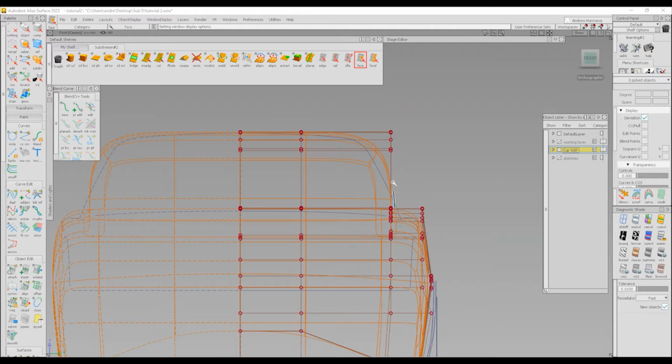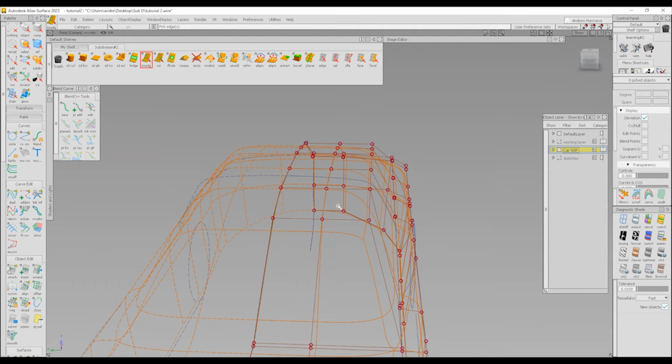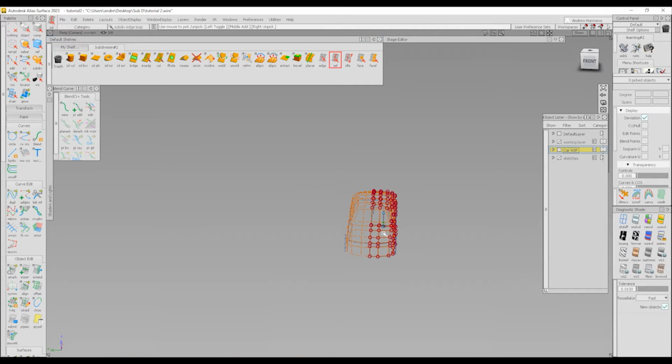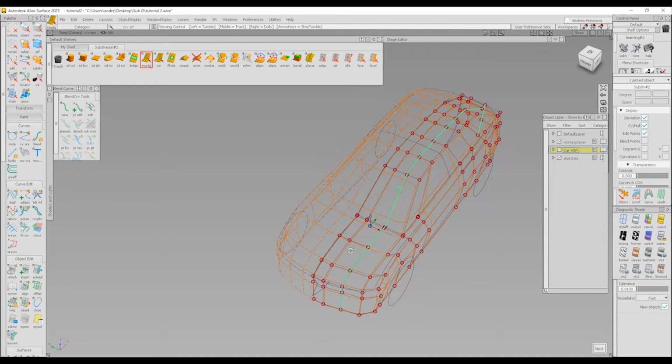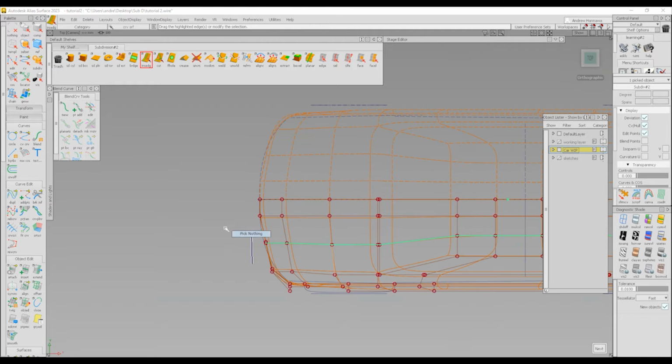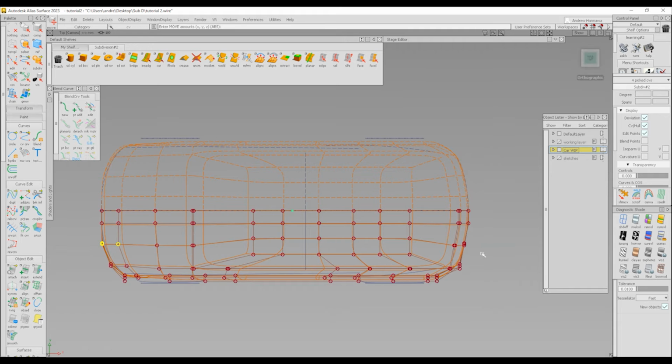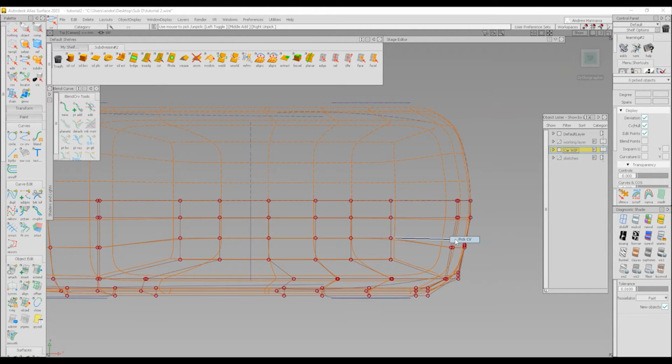We can go into the front view, and then we can add a little bit more tumble home to the car. It looks like we have too much shoulder. We can edit that. And then maybe we can move this symmetry edge loop a little bit further inward, so we can add another one and add a little bit more control in our plan view. So I'm going to be moving these CVs and add a little bit more control, and the same thing in the back.